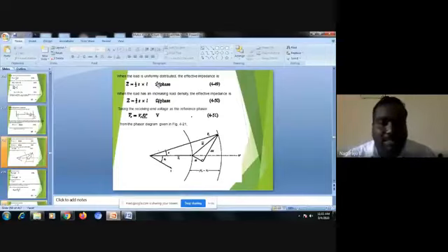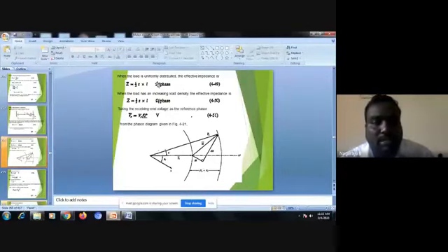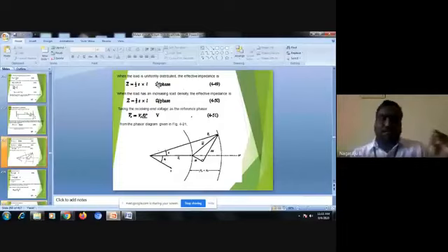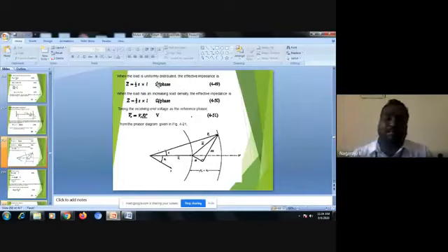When you compare that increasing load density, Z bar is equal to 2/3 of Z into L. It depends on the length, but when uniformly distributed loads are there, it is half of Z into L. When the load density is continuously increasing, the effective impedance is 2/3 of Z into L.